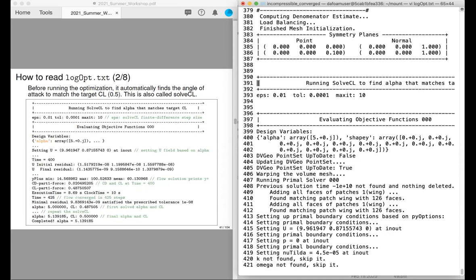May I ask another question, please? Sure. Yes, it's regarding the angle of attack. There you have the lift constraint, let's say, as you have it here on the slide, of 0.5. But let's say you already know what the angle of attack will be, so you don't need DAFoam to calculate that, because you are running a simulation from a baseline design that you already know, for example the existing NACA 0012, where the data already exists on what lift gives you a particular angle of attack.